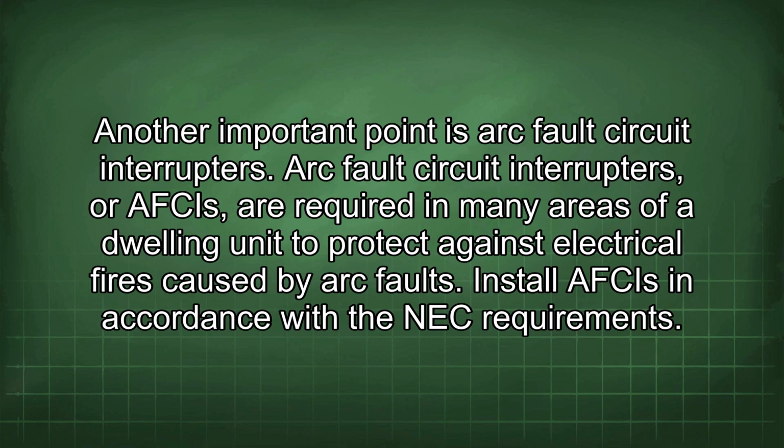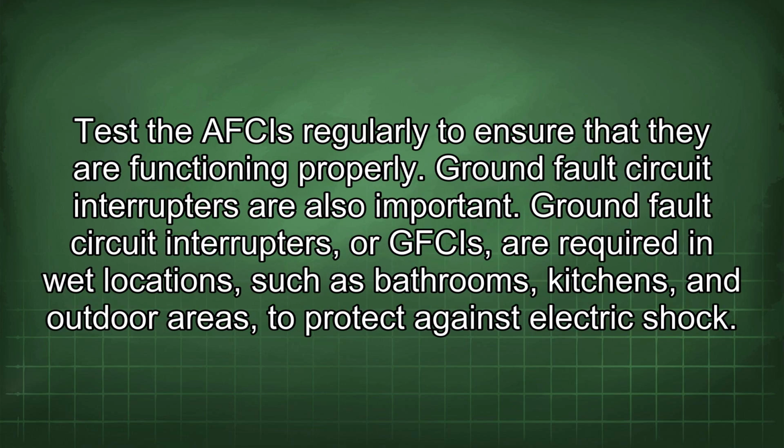Arc fault circuit interrupters, or AFCIs, are required in many areas of a dwelling unit to protect against electrical fires caused by arc faults. Install AFCIs in accordance with the NEC requirements. Test the AFCIs regularly to ensure that they are functioning properly.